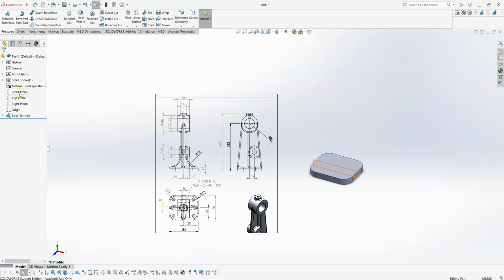If you see now, because I did that as a center rectangle, my top plane is at the bottom of that. My front plane is running through this way. My right plane is running like so. So those planes will be down along the centers of these webs here. That'll make it easier for sketching. I can use the front plane and right plane for sketching.